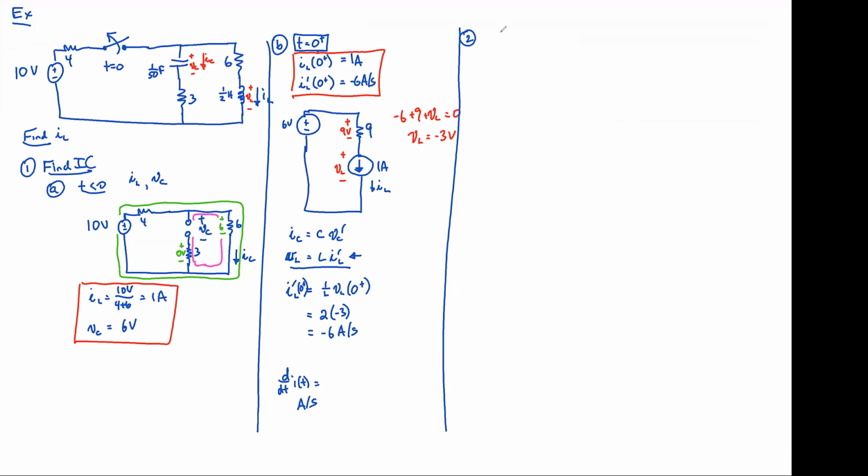So we're going to draw it for time greater than 0 first. And for time greater than 0, the switch is open. There's no current on our left. There is current flowing through the thing on our right. We're interested in the thing on our right, so we're going to draw it. We've got this capacitor. Can't draw it as a voltage source here, because for time greater than 0, it's not a constant 6. It's not a constant voltage source. It's changing around.